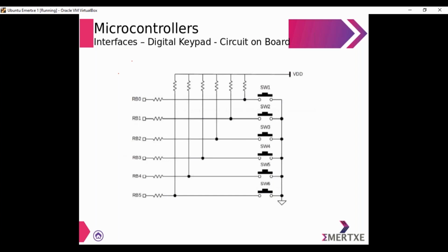Pull-up? Okay. For those who are not able to identify, you see, one end of the switch is connected to the ground like this. Another end of the switch is connected to the microcontroller. There is one resistor here. There is VDD here. And here there is another resistor, and then there is a pin of the microcontroller. So here is the switch.